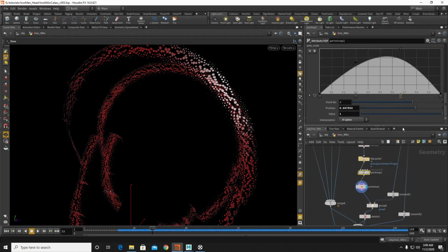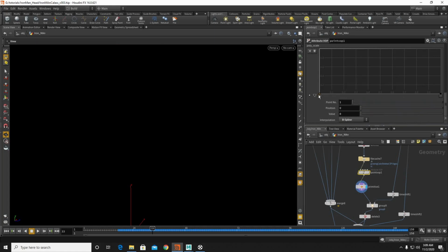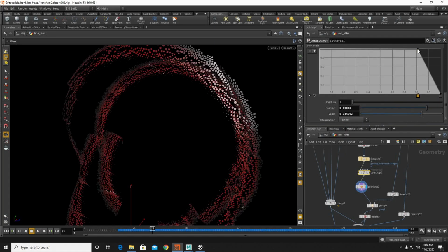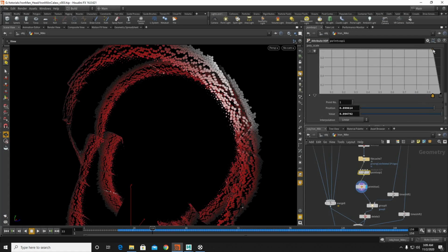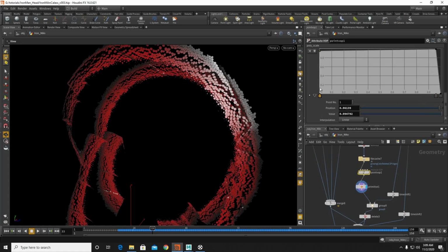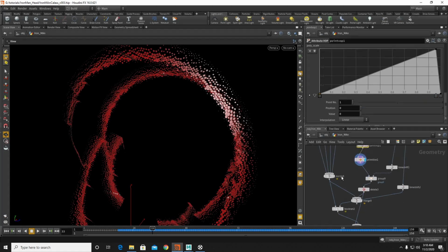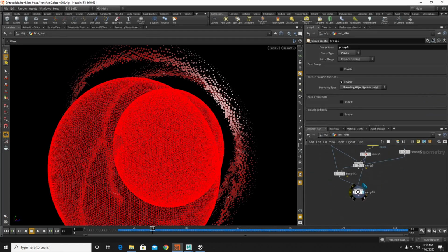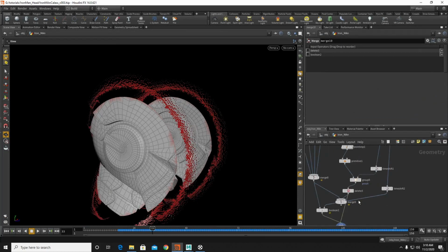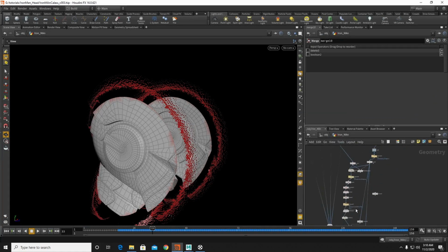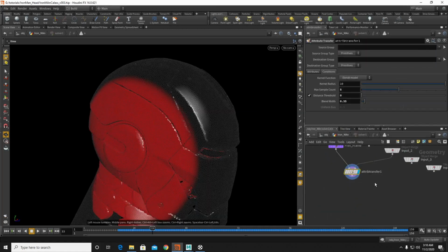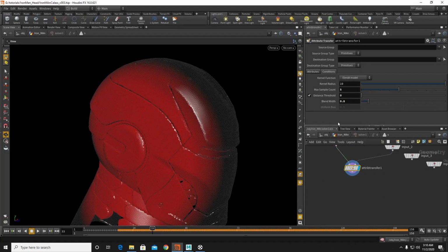Or we can disconnect this and take a curve type. Let's change the curve type, let it be linear, and make this whole thing like this. Yep. And now we can use this. Let's see if it is working or not. It is not working because we need to spread it more. So from here, we can increase this value to 0.5 or furthermore like 0.8, so we can get a gradual increase in the ramp.